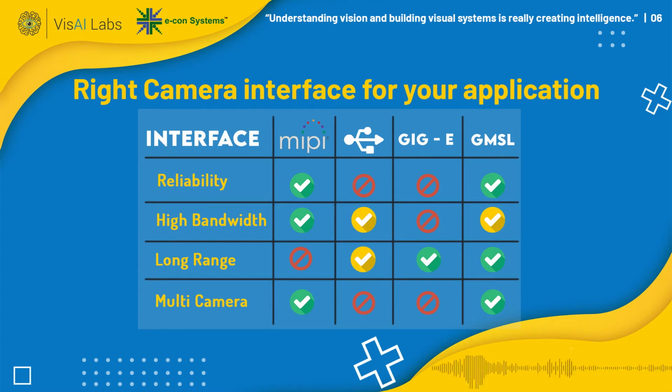Then in terms of bandwidth, MIPI provides higher bandwidth. Just to give an example, if you want 4K 60 frames per second, MIPI would be the only option. If you want 4K 30 FPS, USB would be the next better option. And GMSL, you can go for 4K 30 or 1080p 60 is possible, but when it comes to GigE, usually you won't get that much bandwidth.